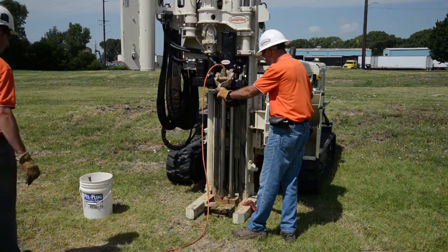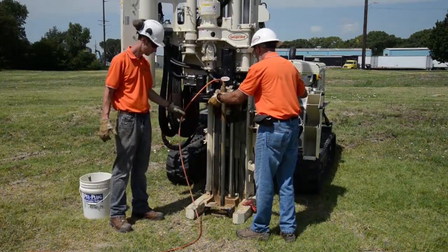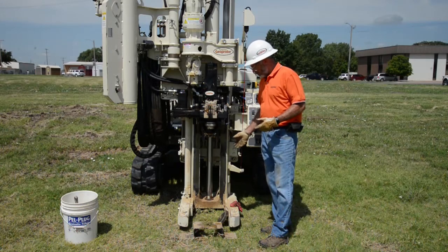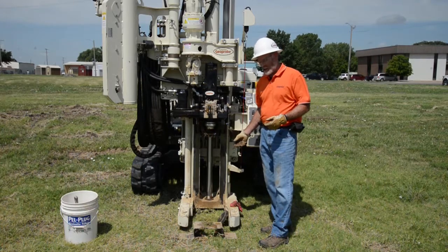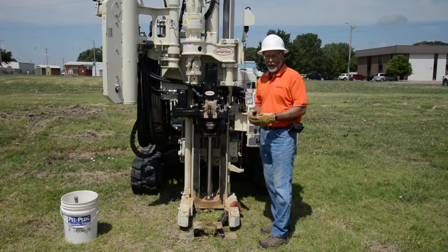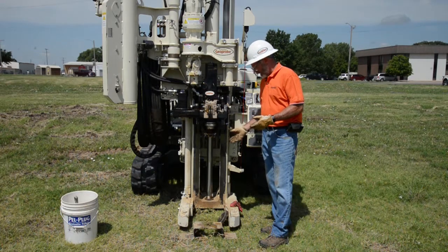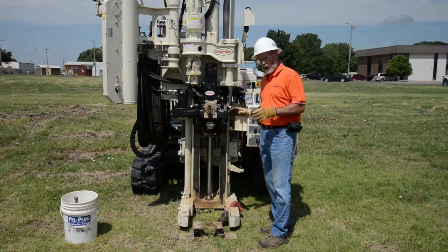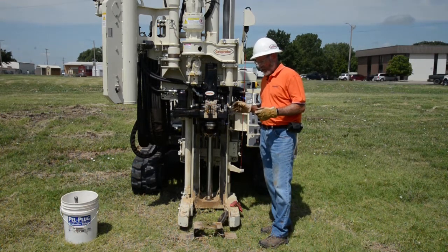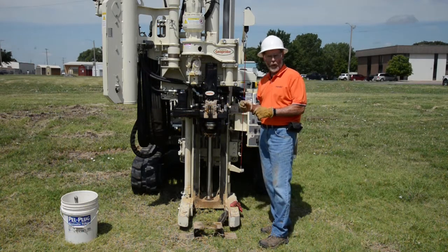Maybe you can see water is still flowing out the port. And we'll clean up and run our post-log QA test. I just want to mention now, to complete the project here, we'd probably want to go back in and do pressure grouting to grout up the borehole, especially if we have any contaminations, especially if we have DNAPLs in the ground. So you can re-enter with a second tool string, expendable point, and we have a grout machine and a grout hose, so you can pump grout through the rods and pressure grout and seal the boring up.